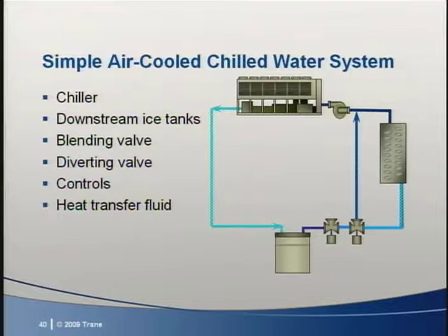Okay, so let's now talk about conceptualizing the system and how ice might be incorporated into a chilled water system. Here we have the storage tanks located downstream of the chiller. The chiller receives the warmest entering fluid temperature and produces a higher leaving fluid temperature. This gives us increased chiller capacity and improved efficiency. That's great for screw chillers, which are more sensitive to making colder water than centrifugals.